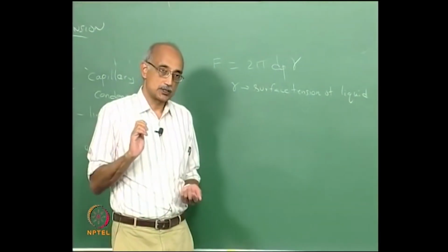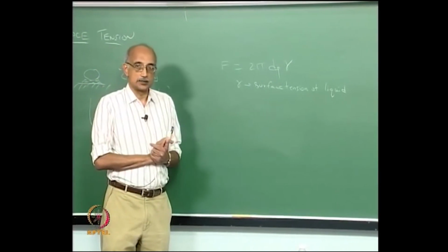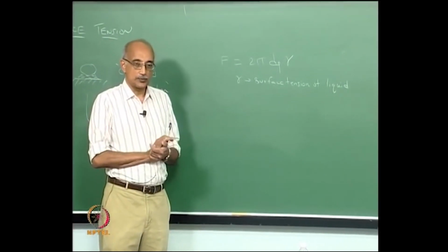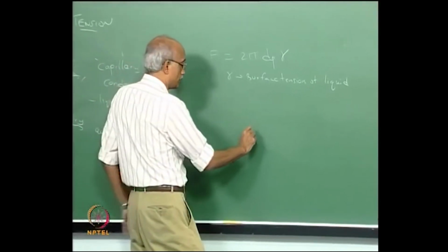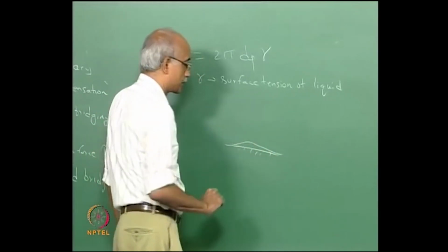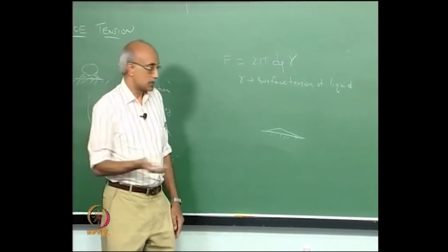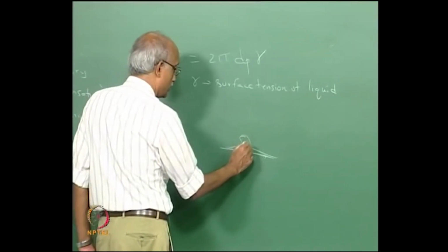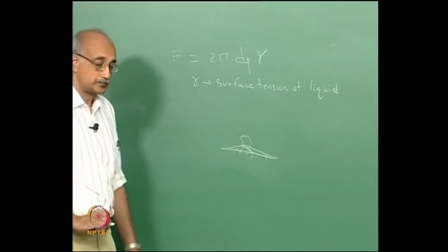Surface tension forces really only come into play when you have low contact angles. In other words, the surface must be capable of being wetted. So, if you have a surface and the liquid does this, then surface tension forces become possible, because now if you have a particle sitting here, you develop this capillary layer between them.